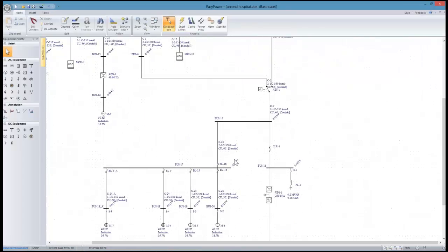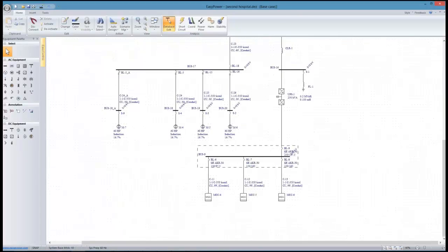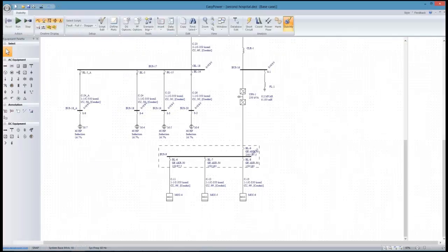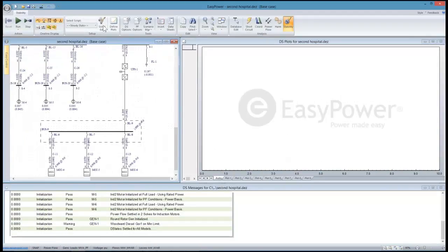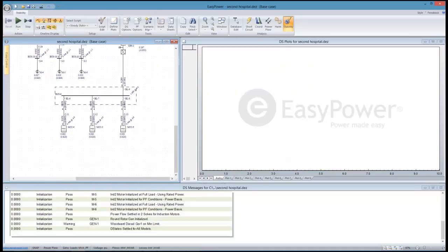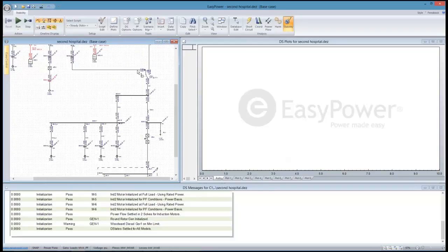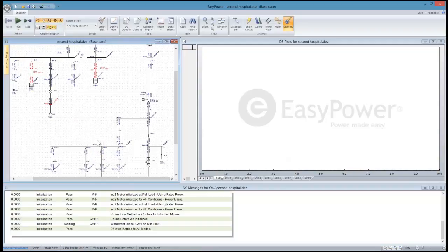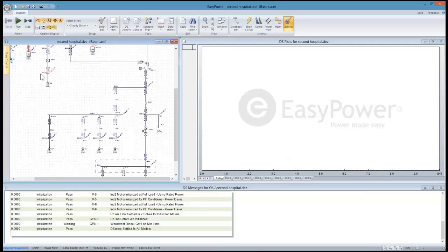If we were to lose power on the main, we'd have our elevator controls and then our mission critical systems sustained by a UPS. So as we go into simulation, or into dynamic simulation, what we want to do is anticipate the potential for a fault on the main bus, the power switching over to the standby generator, and then whether or not all the elevators can be started at the same time and survive, or at least stay online.